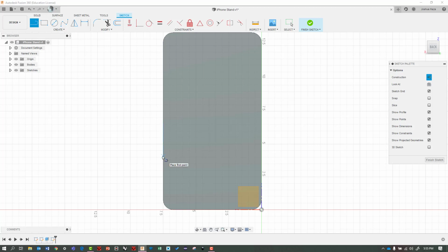Next thing I'm going to do is I'm going to click somewhere on here. I don't care where. I'm going to click, so see how I get the X? That means I'm on the edge of my back. So I'm going to click here. I'm going to drag straight over. I don't want a degree like this. I want it to be a 0 degree straight across until I get, and it snaps to this edge here, and then click again.